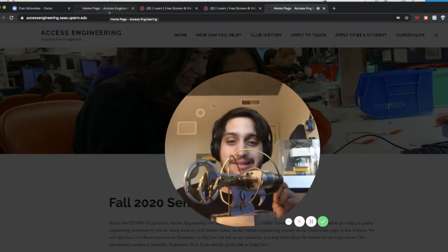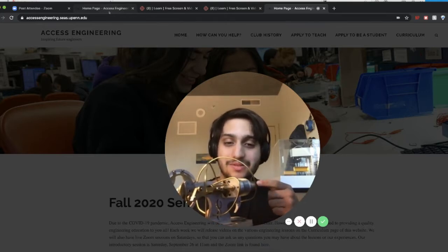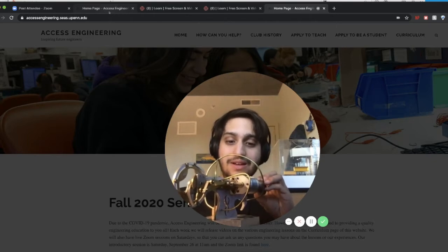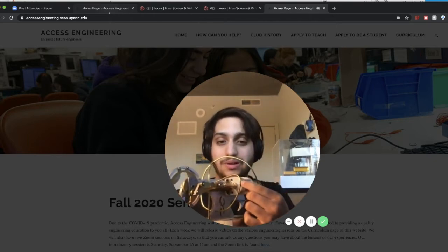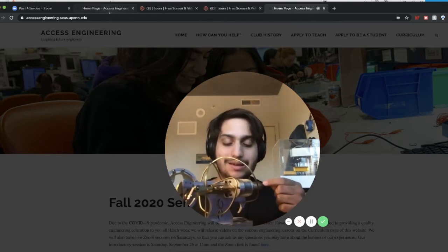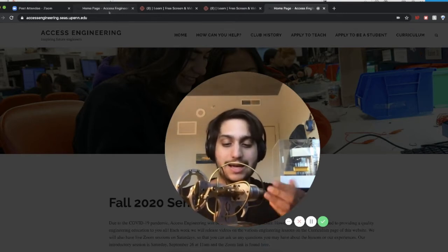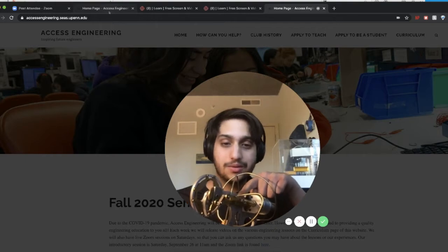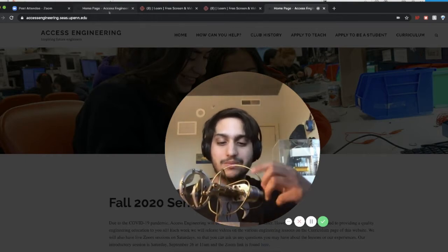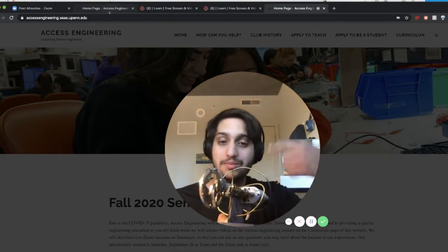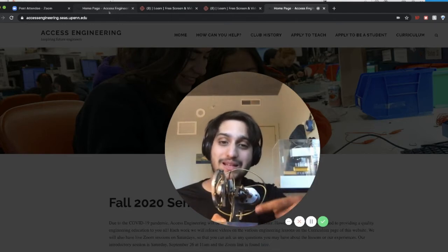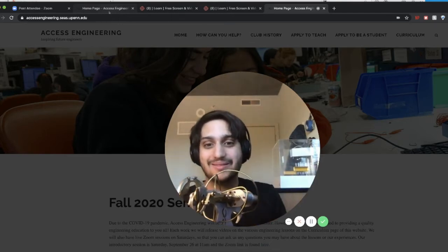Heat is applied to this side. It creates a pressure difference because the particles are moving really fast over here, and pretty cool over here. And so it pushes the displacer over here, cools down, air gets pushed through this tube, and that moves a piston. And so it just keeps spinning and spinning as you apply heat to the side.